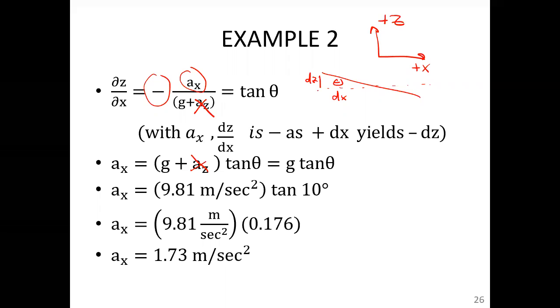And every contour of constant pressure is at a slope of 10 degrees as you move through that fluid. So you can, and we'll go through this in the next example, calculate the pressures and then forces at different locations. So any questions on how we did this? In the second slide of today, I gave you a summary of all the equations.